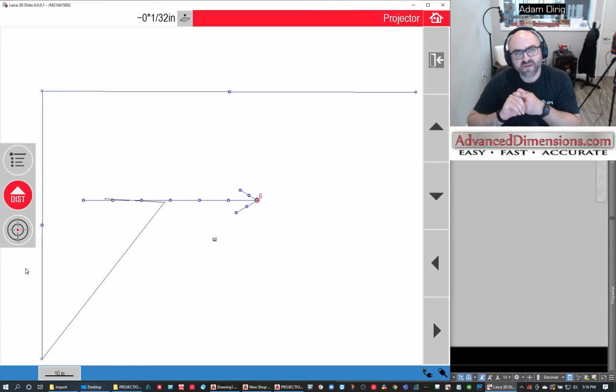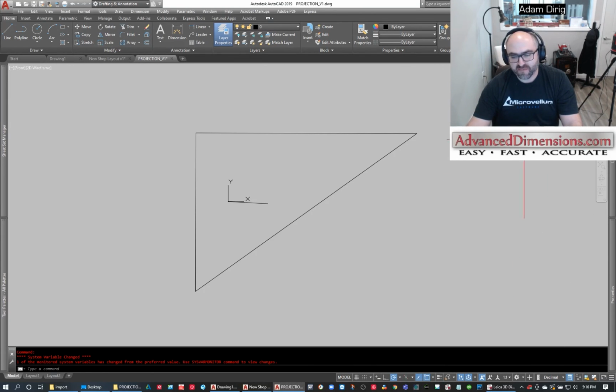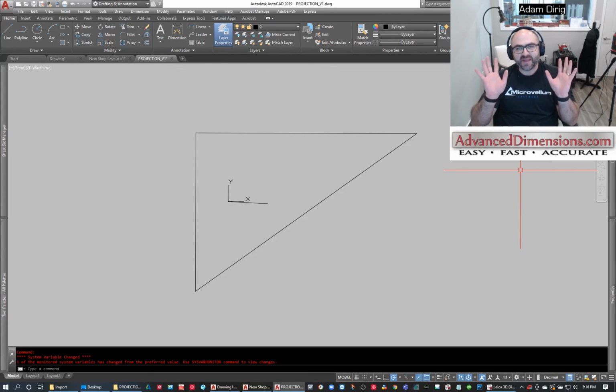So I've thought about this for like anchor bolt locations or anchoring locations for like wall paneling, for anything like that. It's an extremely powerful feature, but the biggest thing that you need to remember is in CAD, you need to make sure that this is set up for a top-down view and that it's saved that way as the DXF file. And then you need to import it in, and it needs to be less than that 2 megabyte size.